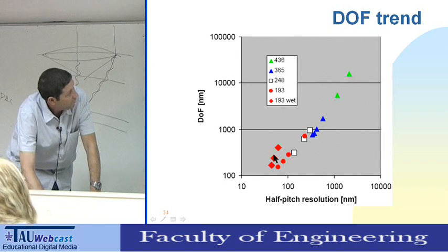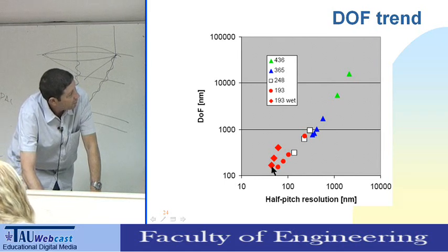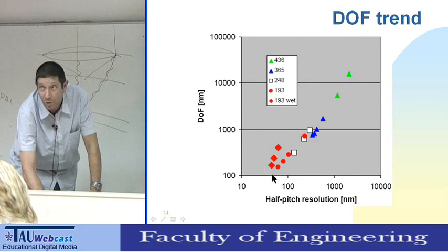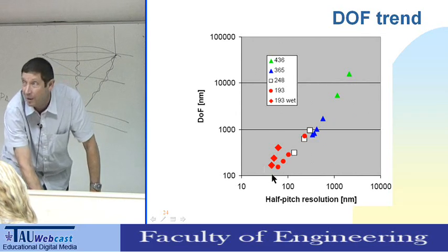This is wet. With wet lithography or immersion lithography, you can get the same resolution but much better depth of focus, or with the same depth of focus, much better resolution. This is practically what you gain.